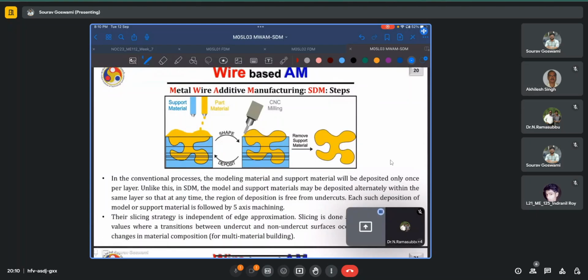Now, this is the shape deposition manufacturing that we were discussing, and we have encountered the step of segmenting. Unlike slicing, which occurred for fixed layer thicknesses or adaptively, when we wanted to accommodate some intricate geometrical feature, segmenting occurs only on the consideration of where the overhanging region is being introduced, or if I'm continuing with an overhang, where the non-overhanging region is being introduced, or if there is any undercut feature.